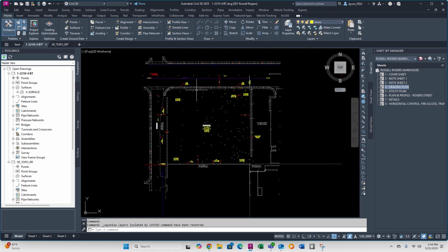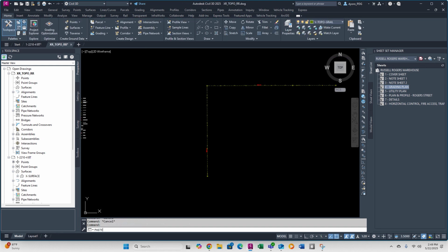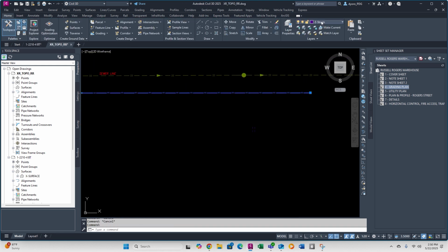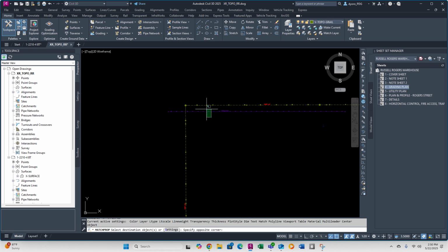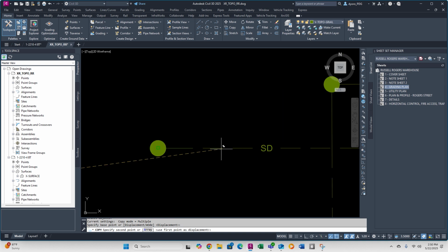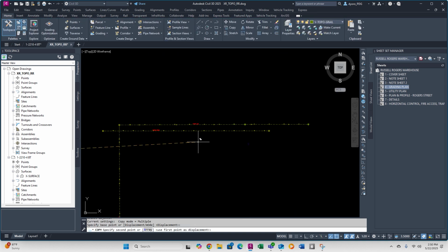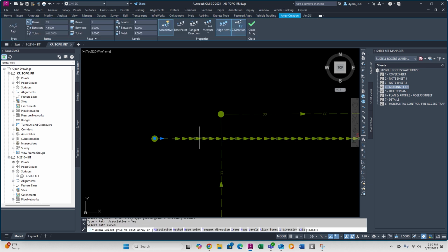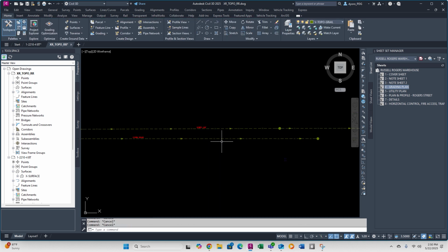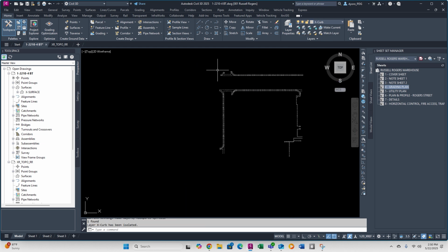Then I'm going into the topo drawing of the surveyor and deleting the line work that I've brought in. Keep in mind that I'm not saving the boundary and topo drawing. This is just so that I could see what's left to bring over and to make sure that I've got everything on our layers and not missed anything. So I'm just going to fast forward through this part. As you can see, I'm just putting everything on our layers and putting everything on the vAnno layer, that's annotation, and just bringing everything in, making sure I don't miss anything.